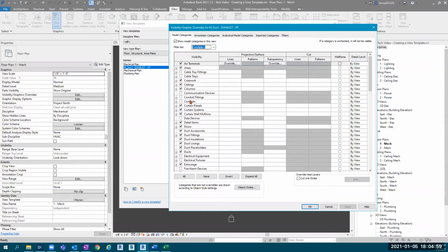So when it comes to mechanical, this is where we can set all our information. So if you're trying to compare CAD notes to how Revit works, this would fall under something similar to a layer. However, this will be a portion of that layer as opposed to contributing to the whole layer that you're used to in AutoCAD. Think of Revit as breaking that layer up into sections, using those model categories, and then also utilizing options out there such as filters and other things such as systems in order to break up the full visual effect of those categories.